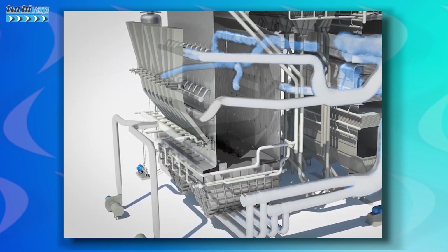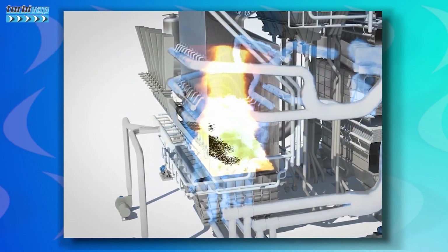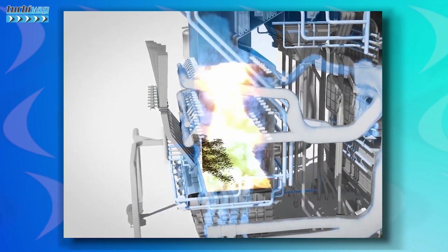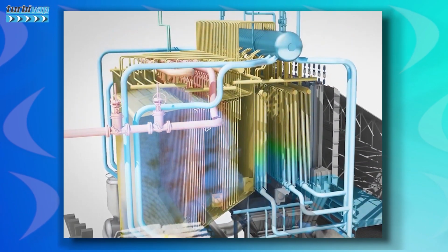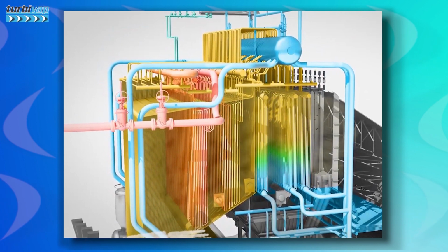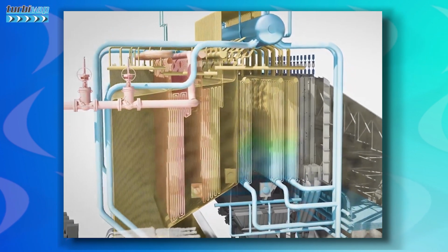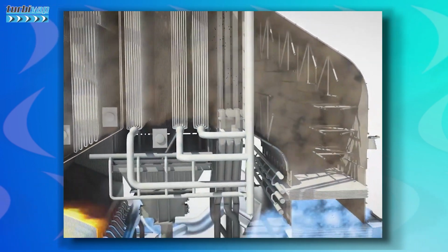Later, as we will see in detail, the steam may still contain energy to be used in other processes, in the case of counterpressure turbines, or it may no longer have energy to be converted and reused, as in the case of condensing turbines. In the latter case, the steam returns through the turbine exhaust to the condenser, where it is condensed. Roughly speaking, it is turned into water and pumped into the boiler again, thus restarting the cycle.